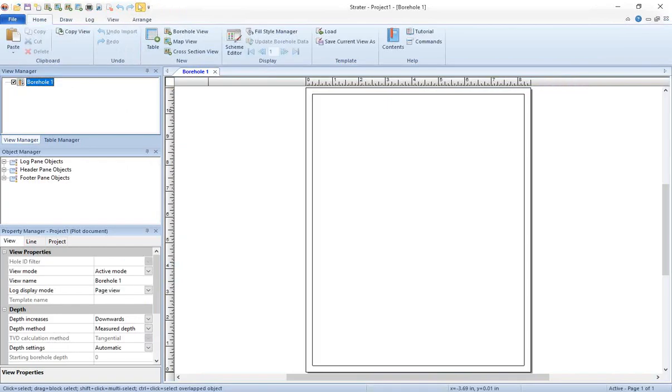All right, and so this next example is going to be based on how to create a cross-section from a lithology log or a zone bar log, in which these are very similar log types. The lithology log allows for weathering and indentation on one side. That's about the only difference between the two log types. All right, and so the steps are going to be the same for each log. So it doesn't really matter if you're using lithology or zone bar. This workflow will apply to both.